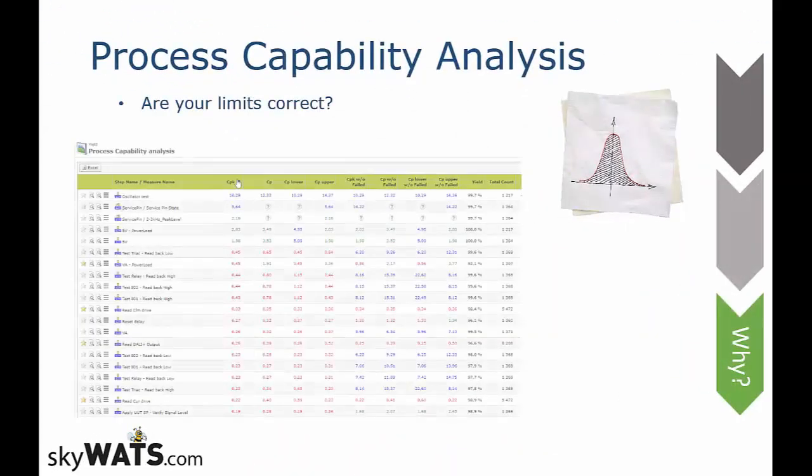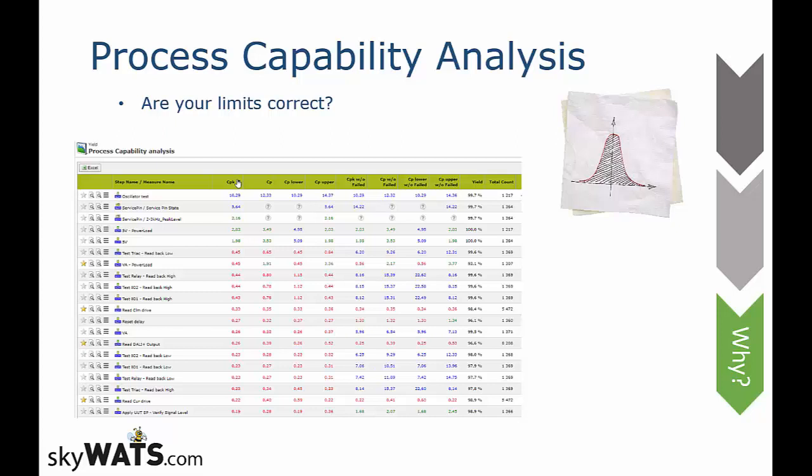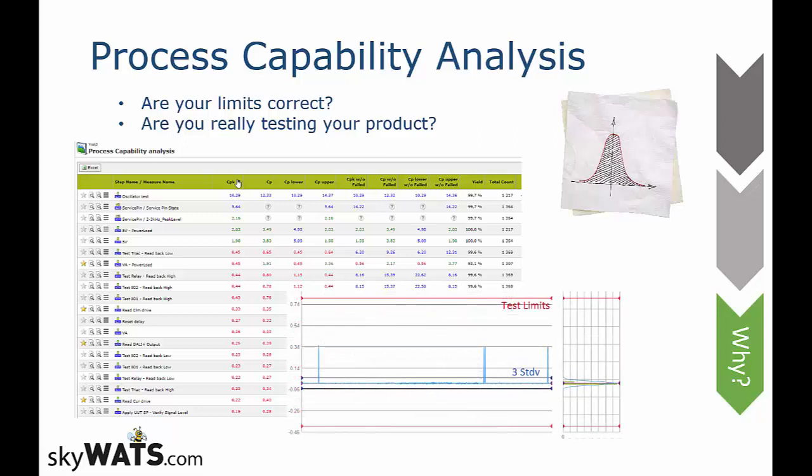The process capability analysis reports help to understand how well your test limits compare to the process variations from the individual test measurements. The easiest way to get a good yield number is to have extremely wide limits, although this is likely not helping your quality go to where you want it to be. The values found here are also useful in assessing how valid your yield results are and can be fed back to make sure that you have good test coverage. In this example, you clearly see outliers in the data that should have been detected during test, but the limits were too wide.